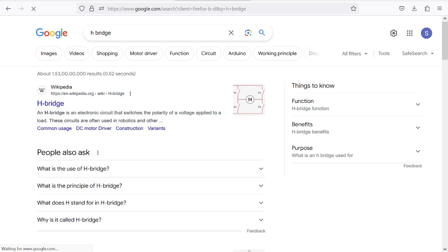So how do you find the duty ratio? There is this 16 volt and the input voltage is 48 volt. So Vg is this much and we want the voltage across the motor to be 16 volt. How to approach this problem?